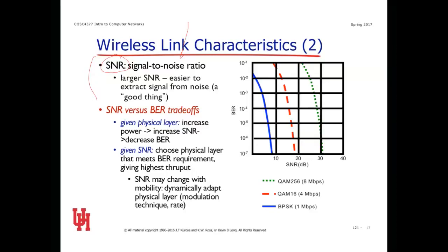And then there's bit error rate, which is another complication, which is the data is weak when it arrives, but it's also corrupted when it arrives because it's been subjected to errors. So things that were ones are zeros, and things that were zeros are ones. Qualcomm Corporation out of San Diego, I think, for their headquarters, did a lot in this area to come up with new math algorithms that allow you to still recover useful data from a corrupted, low SNR signal. You can still pick stuff out. And so their technology is used in most communication systems.